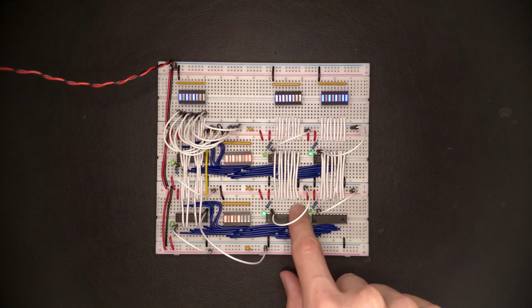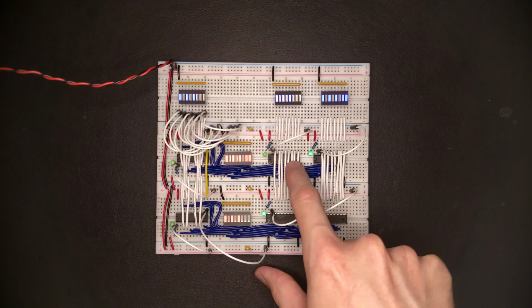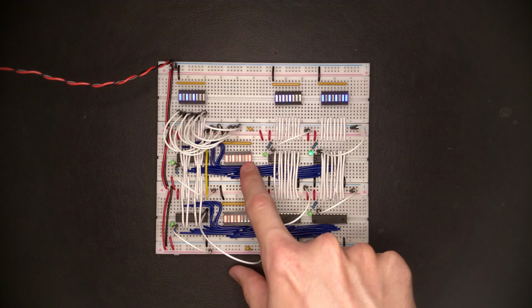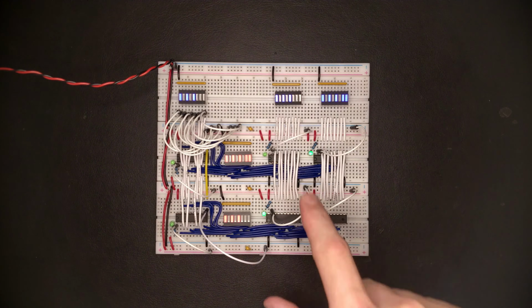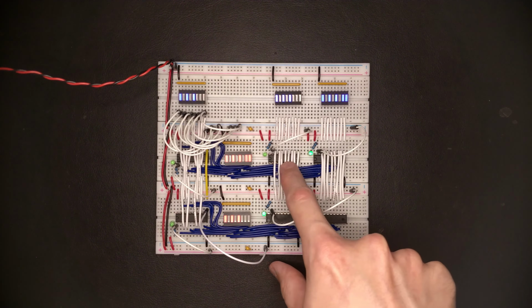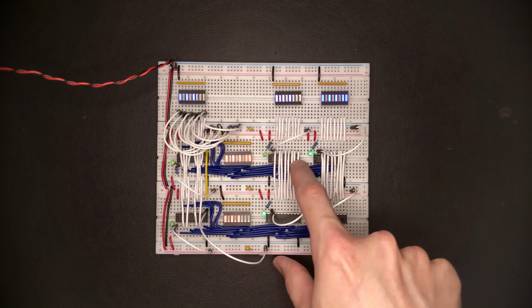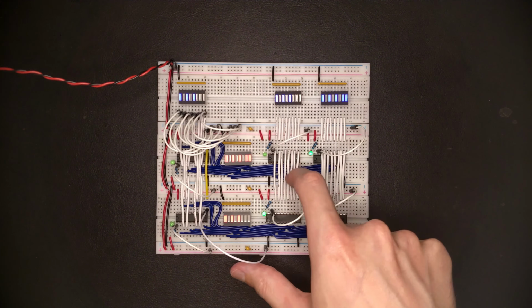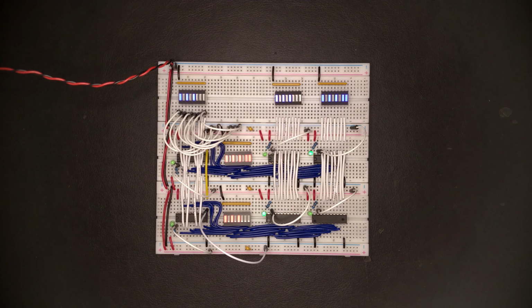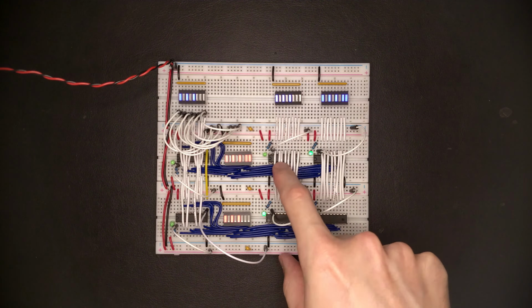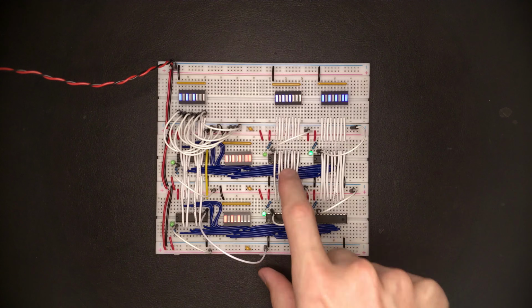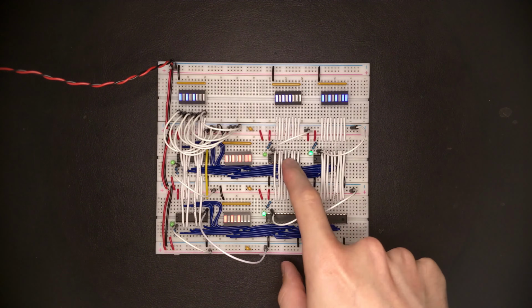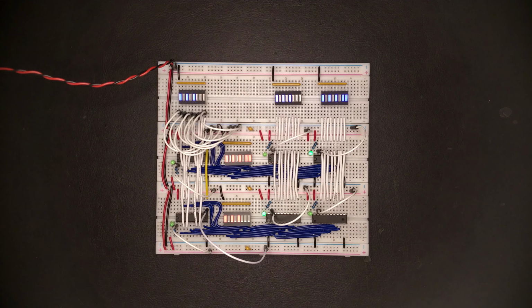So there will be a driving conflict on the last two lines here, because this buffer is trying to pull them down to ground, and this buffer is trying to push them up to VDD to represent the 1. And what will happen is basically this buffer here will connect the least significant bits to VDD. This buffer will connect them to ground, and you end up with a short circuit through your system. So what we want is to only ever enable one single driver of this read data bus, and we want a mechanism to select which one of these is responsible for producing an output.